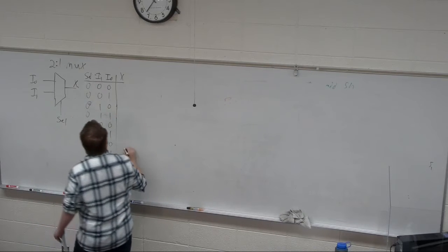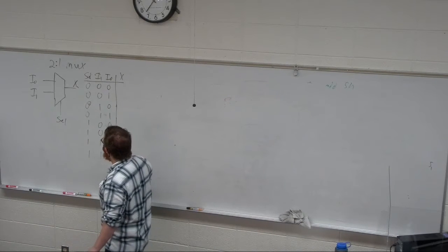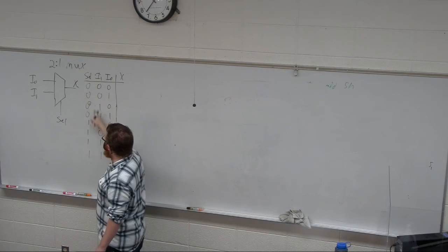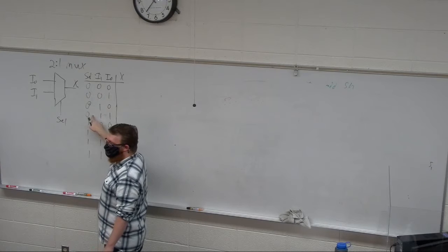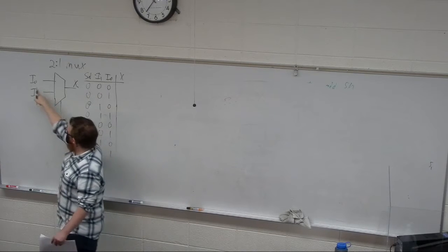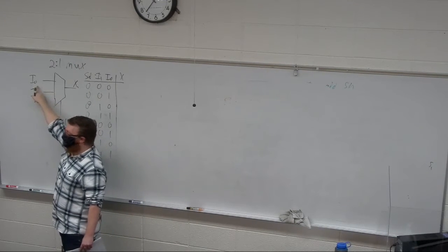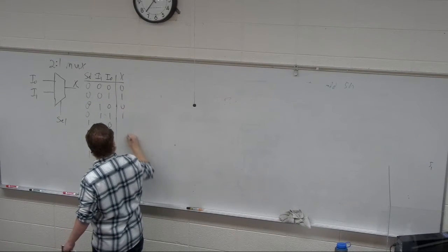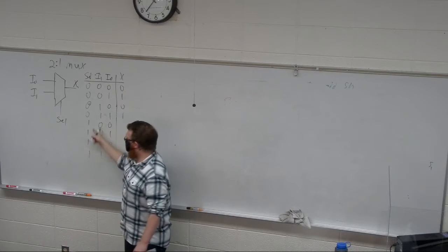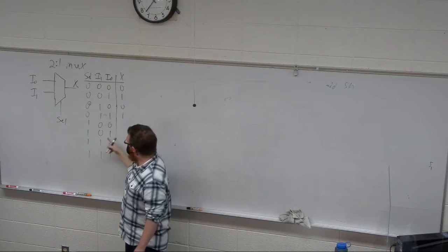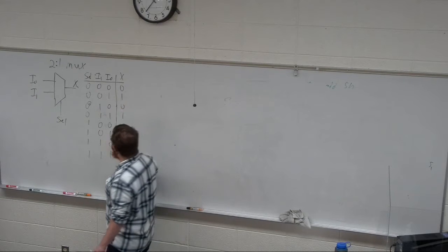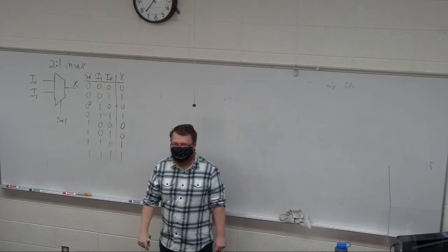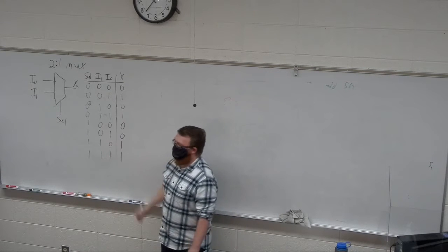Okay, there we go, truth table. So the only thing that matters, right? Well, the first thing that matters is what is select. So if select is 0, I care only what I0 is. So select is 0, I0, X is just going to do that. Similarly, if I have select, then I only care what I1 is. Ta-da, right? There's our truth table for a mux.